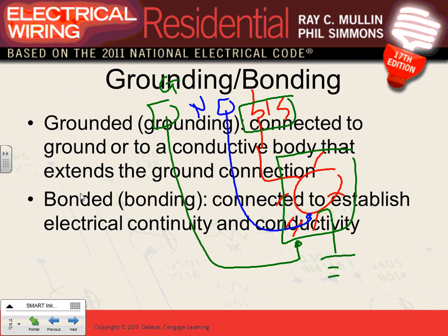So that's where the ground is. It facilitates the operation of the circuit breakers for residential, commercial, or industrial. Everybody's okay with that one? So that's why we ground the system. Every system has to have an equipment ground conductor, with very, very limited application.